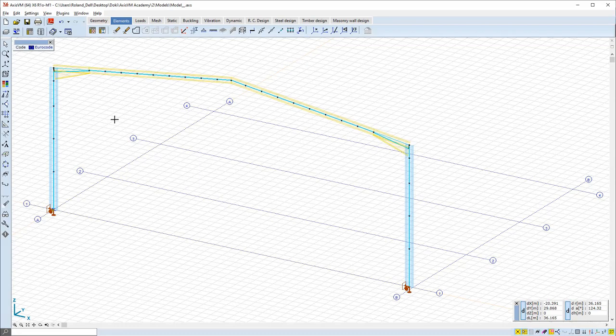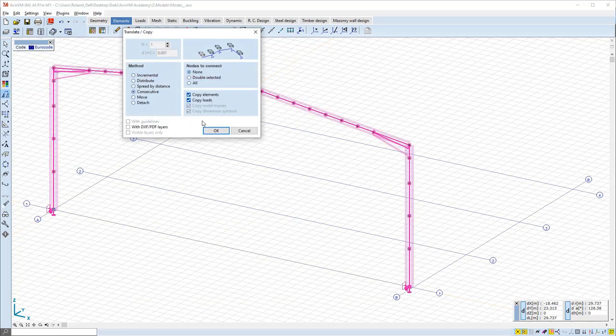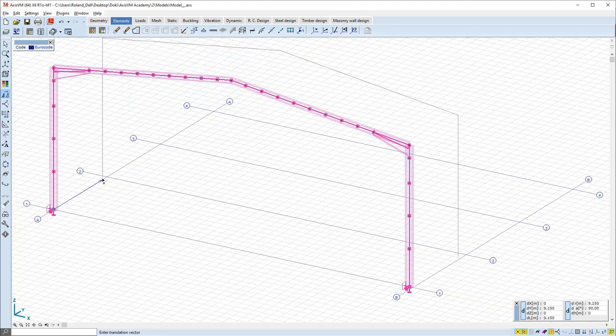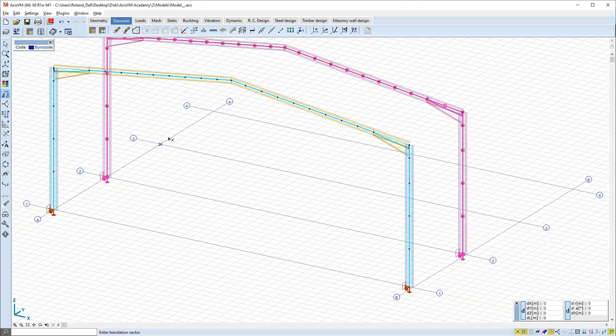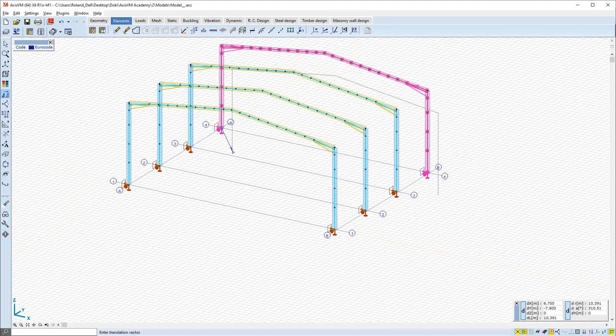In the last phase of the presentation, we will show what the peculiarities are when the same frame is used in a 3D model, where the secondary load-bearing system is modeled with actual purlins instead of nodal supports, and we will see some model handling, selection and modification practices as well. The whole will have 4 frames in 10-meter distances, and positions of the columns are designated by the structural grid. Intersection points of the grid serve as snap points for the cursor as well when copying the frames consecutively.